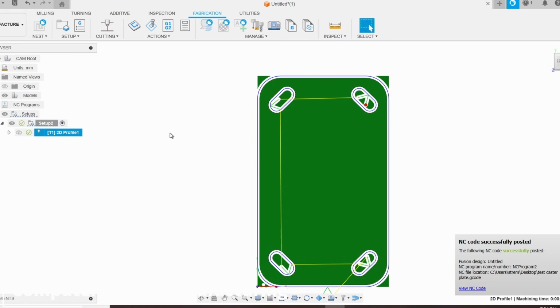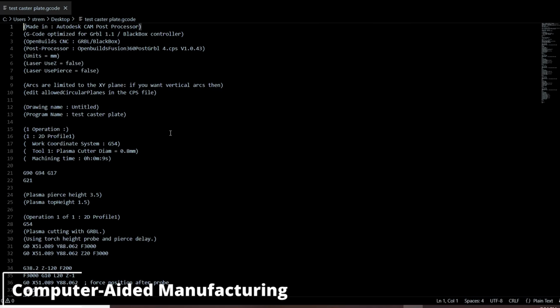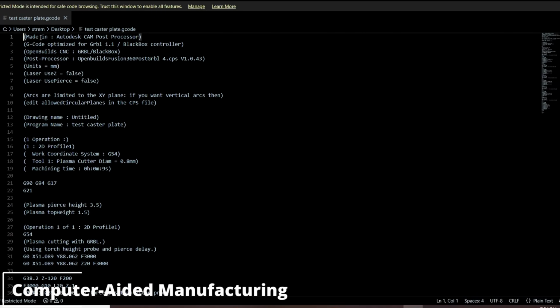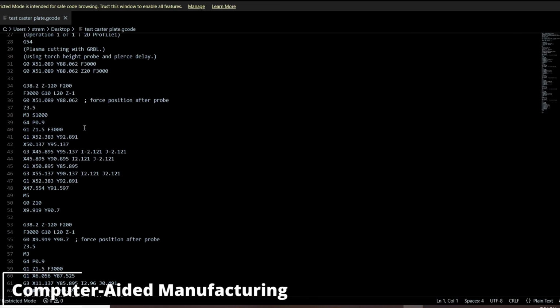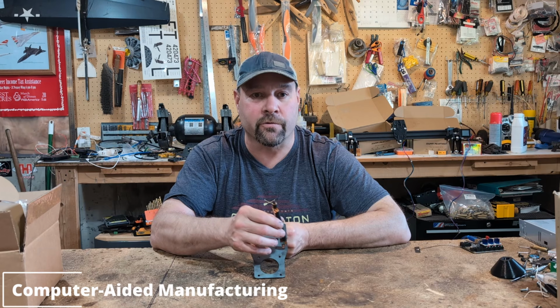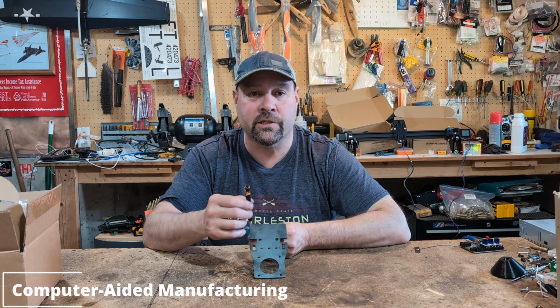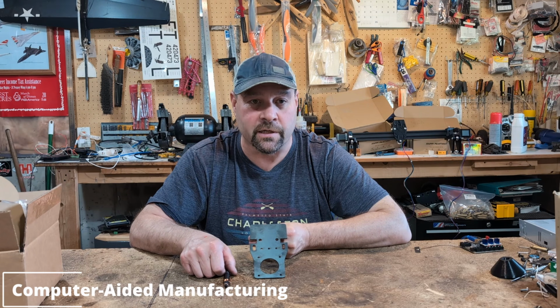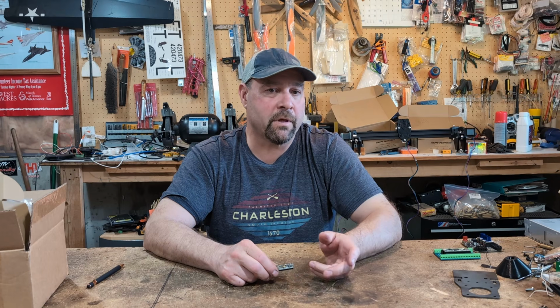Now, the post processor is specialized based on the type of machine you're running. So in our plans, we have a post processor to add into Fusion so you get the right output of G-code to send to the machine. We have the CAM running through the post processor. It creates the G-code that the machine is going to use. So we covered the first two software already. We're going to skip the third for just a minute.